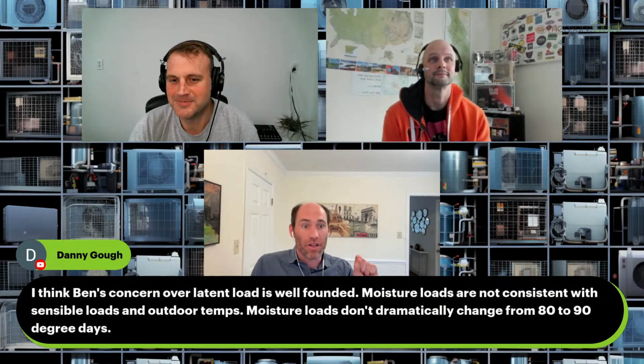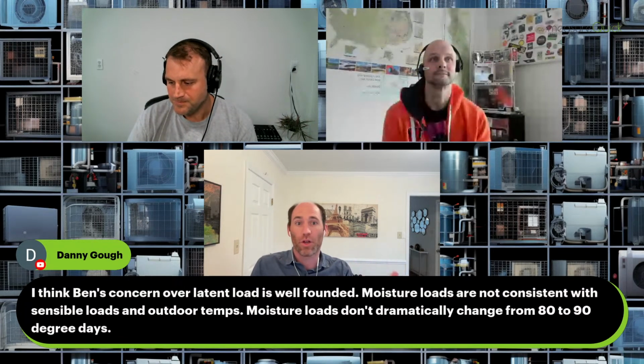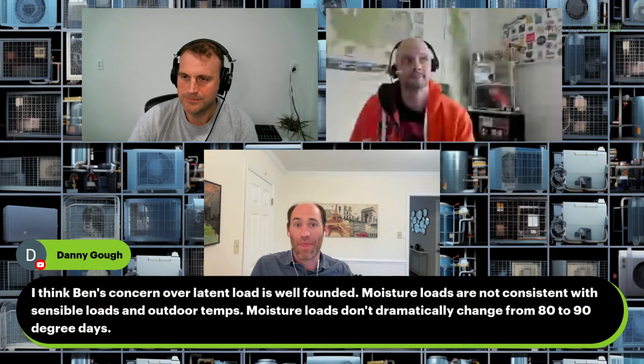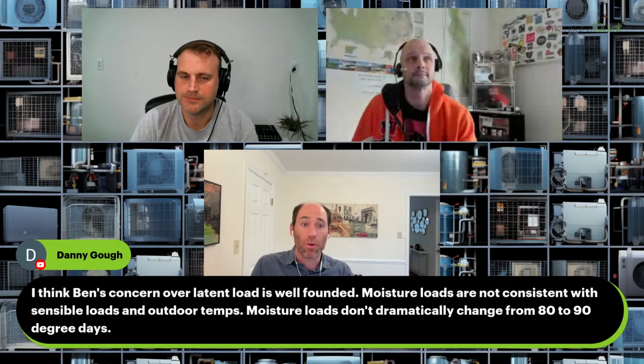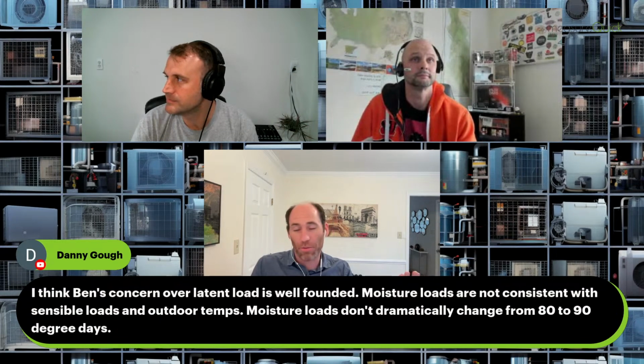But it would need to ramp down when the dew point is high and the sensible cooling load is low, be able to remove more moisture, sacrifice a little bit of efficiency, and get that water out, and prioritize the water removal. The equipment can do it, but the controls are just dumb, in my opinion.